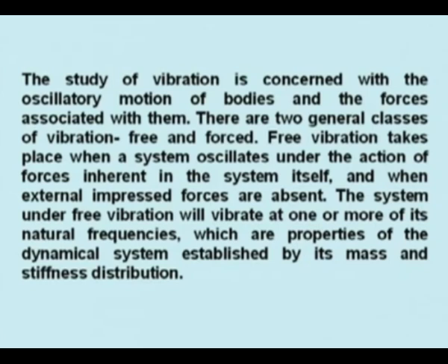But at the same time you may have another example where there is a disturbing force. It is like if you travel in a bus. The bus is traveling, the road is rough, so because of the rough road, the forces are transmitted through the tires and come up to the seats, so you feel those types of vibrations. So there are vibrations that may be because of some external force, or without external forces also, a body can oscillate between two positions.